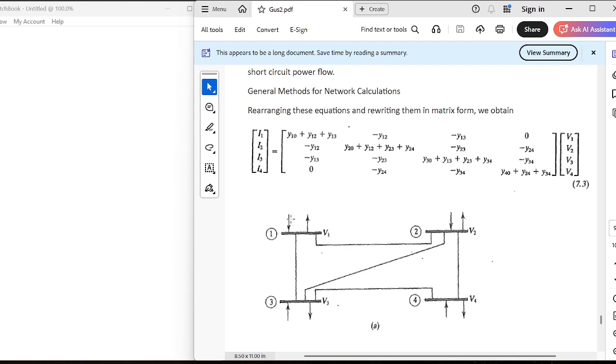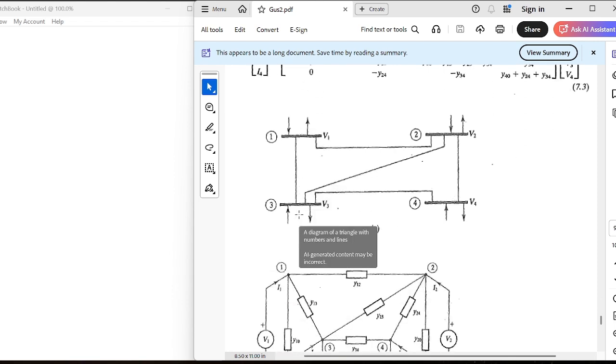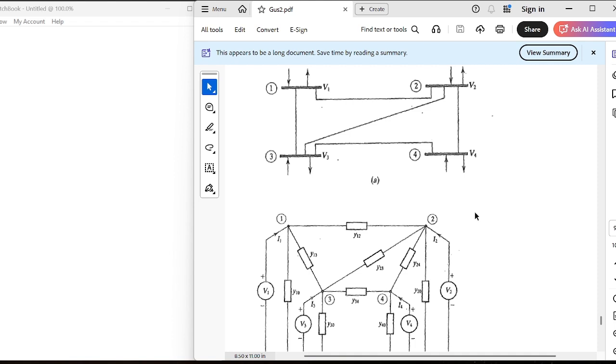You've got current in, current out, and you've got crossing of these bus bars. So you get these motor control centers. Here'd be a motor control center, here'd be a motor control center, here'd be a motor control center, here'd be a motor control center, and here's the cross feeding between them, and here are your admittances between them. From that you can find the current available in 1, in 2, in 3, and in 4. So that's your I1 through I4. Okay, and there's how that's done.